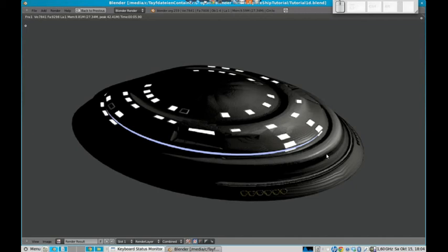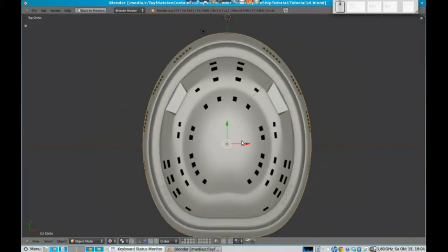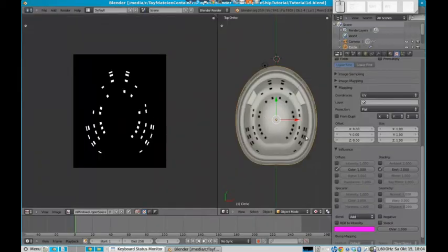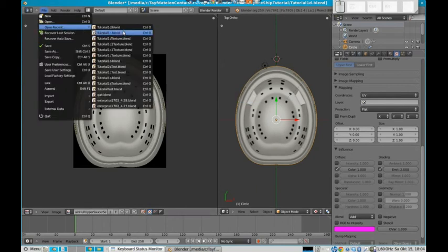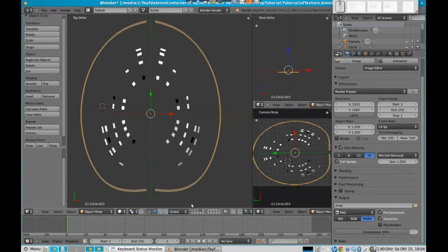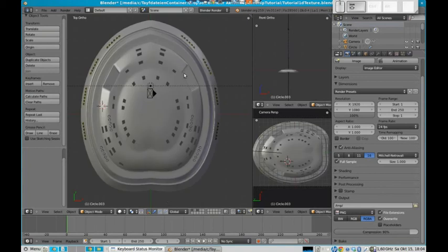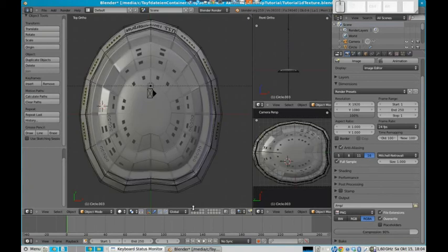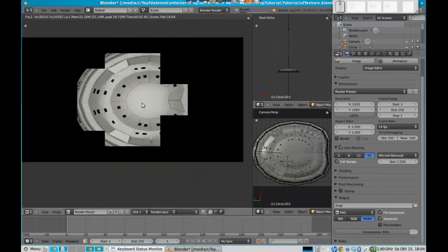The grid is missing. The grid is definitely missing. Of course, the grid is not here. So let's save that again and go back to 1D texture and go back to layer 3 with the lamp and layer 1 with our file, and let's additionally activate layer 2 with the grid and reanimate it. So previously I just forgot to add the grid.